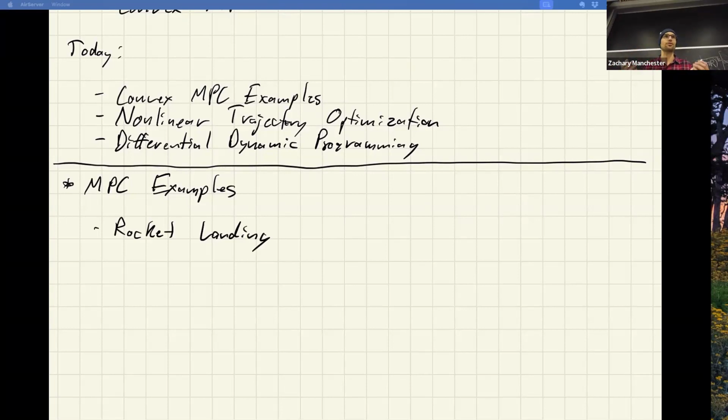This is actually a really huge result, one of the major advances in the field about 10 years ago. There's a paper on this by 2 guys, Lars Blackmore, who runs the controls stuff at SpaceX now, and Behcet Acikmese, who's now a professor at the University of Washington. These 2 guys, super cool. One of the major results of the last 10 years. The basic idea is you model the rocket as a point mass in this setup. The reason you get away with this is you can separate the attitude dynamics from the center of mass position dynamics.